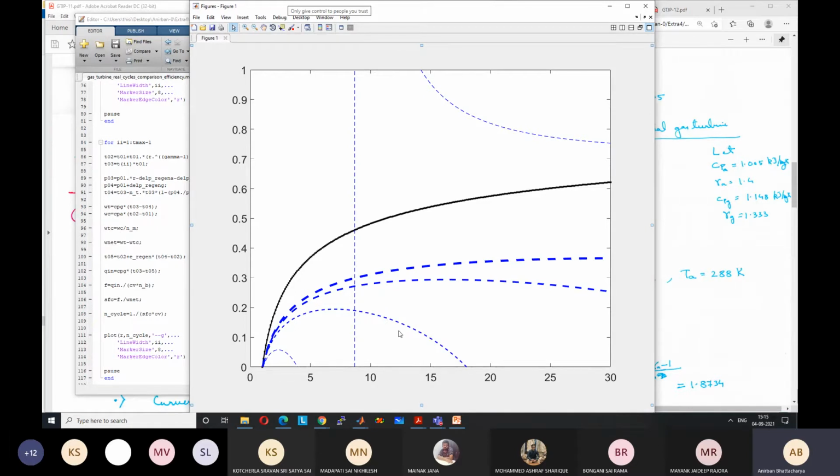Okay, so much less. So this is another observation. Then what we also see is that the optimum value at which the maximum efficiency is obtained shifts towards the right hand side, and there's a large flat region over which the efficiency almost does not vary much, at least for the higher temperature ratios. We can see a large region, meaning we have some flexibility in taking the value of R. So for example, if the temperature ratio T is 5, it will not matter much if we take R as 20 instead of 30.